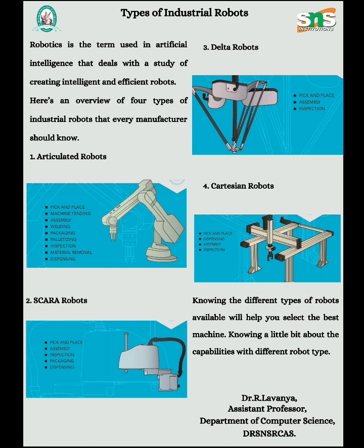Due to their fixed wing arm design, which is an advantage in certain applications, SCARA robots face limitations when it comes to tasks that require working around or reaching inside objects such as fixtures, jigs, or machine tools within a work cell. The third one is the delta robot. It is also referred to as a spider robot.